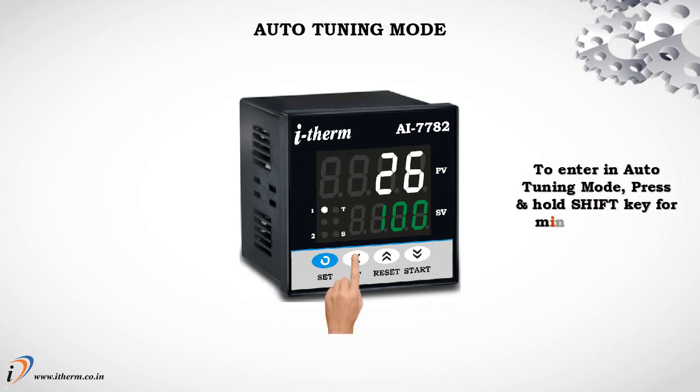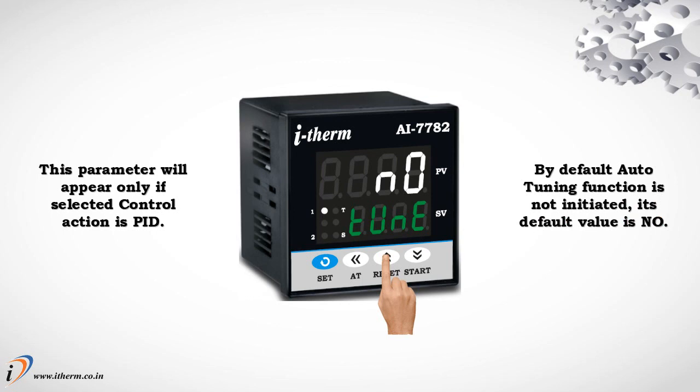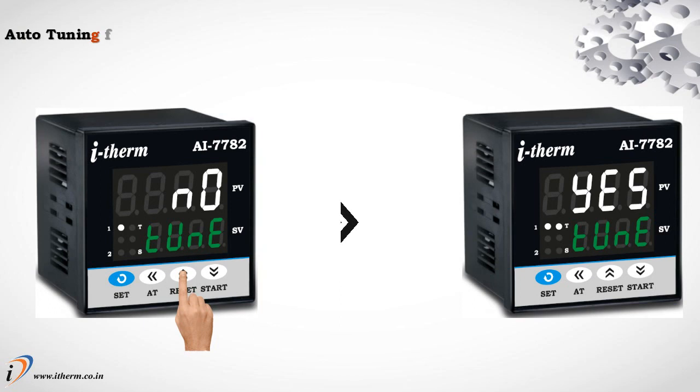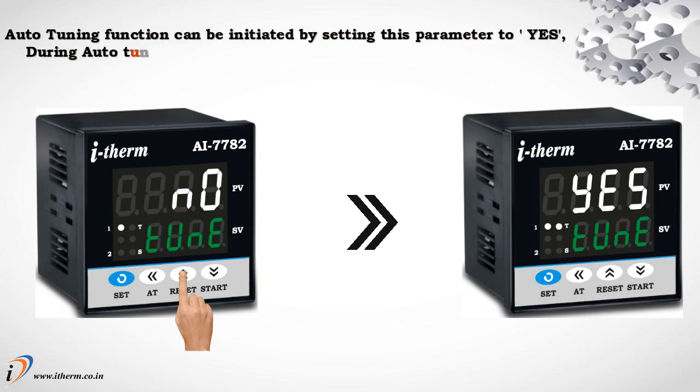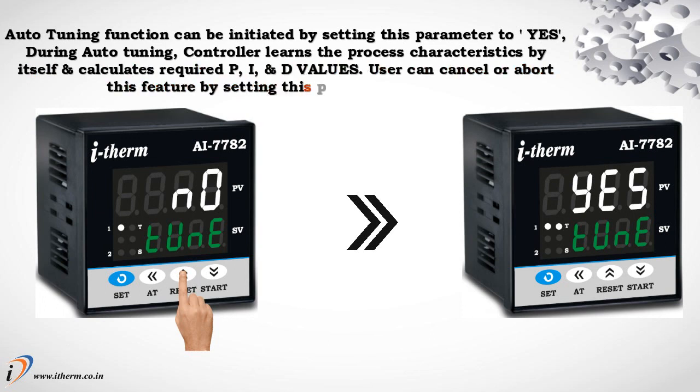Auto-tuning mode. To enter in auto-tuning mode, press and hold the Shift key for a minimum of 3 seconds. This parameter will appear only if the selected control action is PID. By default, the auto-tuning function is not initiated. Its default value is no. The auto-tuning function can be initiated by setting this parameter to yes. During auto-tuning, the controller learns the process characteristics by itself and calculates the required P, I, and D values. The user can cancel or abort this feature by setting this parameter to no.